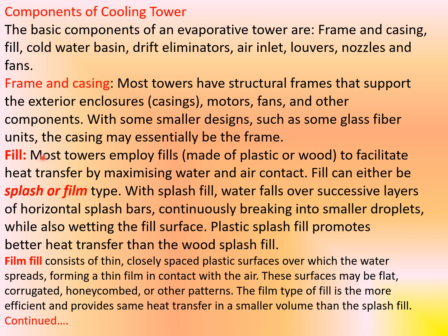We need a filling material through which the water gets down from top. The hot water is circulated from top, and it goes slowly up to bottom through a fill material which may be made of plastic or wood to facilitate heat transfer by maximizing water and air contact. Fill can either be splash or film type.